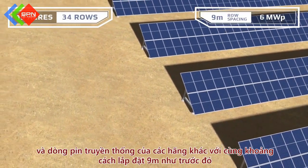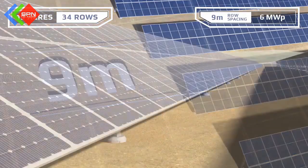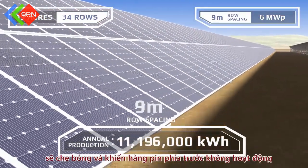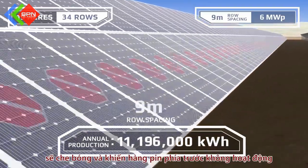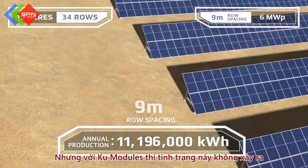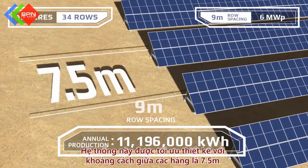Our competitors can still only tolerate the 9 meters spacing we saw before. Notice that at the beginning and end of the day, shading from the adjacent row knocks out power production from an entire row of modules. But with Ku modules' better shading tolerance, the system design is optimized at 7.5 meter spacing.